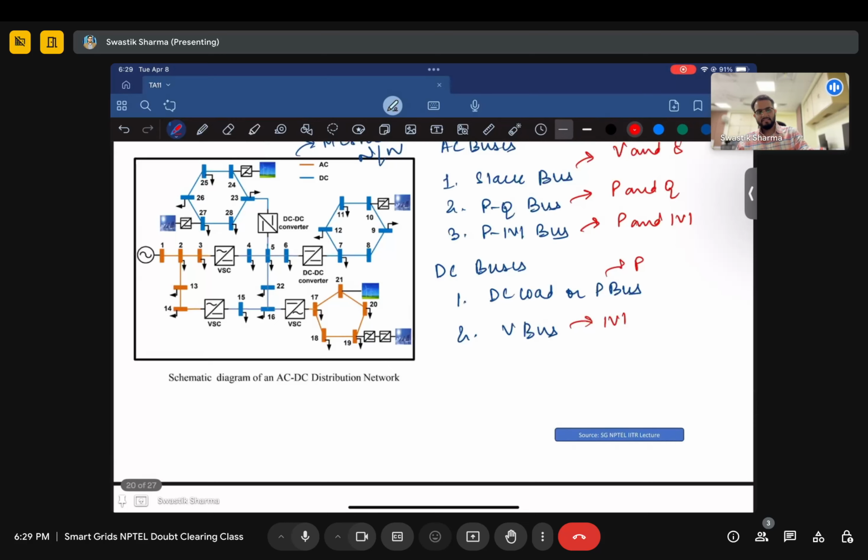Now, we've discussed that conventional load flow suffers here because we have power modeling issues because there is a high R by X ratio. But the other thing that we need to do is model how the DGs are consuming this power. So we need to model these individual distributed generations available, these wind farms, and the converters, the voltage source converters, and this DC-DC converter. All of them need to be modeled properly, and if we have storage, if at all we require one. So these are some issues that we face.